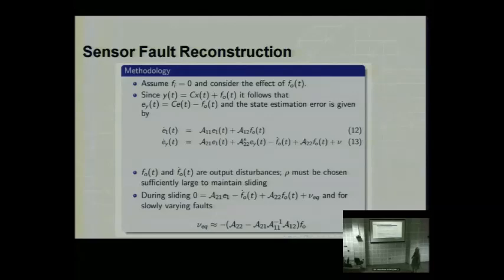and the fault. And what you actually see by clever looking at the channels, you can see you can get almost everything. So whether you have a sensor fault on the first output, the second output, the third output, you can get all the information about those faults by appropriately looking through the channels, bearing in mind that one of the channels is effectively giving you the derivative of the sensor fault. Okay? So it's effectively giving you the derivative of the sensor fault.